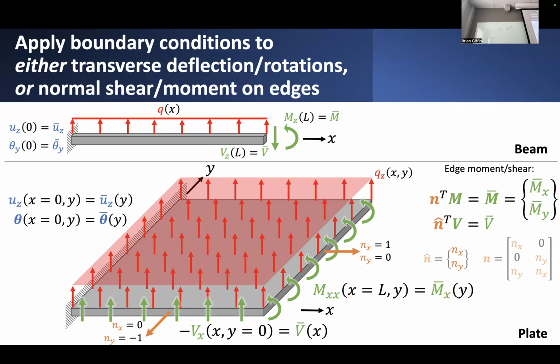You can relate this edge normal, multiplied by the vector of all these different components of the stress resultant quantities. Those are the MXX, MYY, and MXY quantities. And you can only specify two of them, really. You can either specify a moment like this that would lead to bending, or you can actually specify almost like a twisting, bending, torsional moment on these surfaces, kind of interestingly.